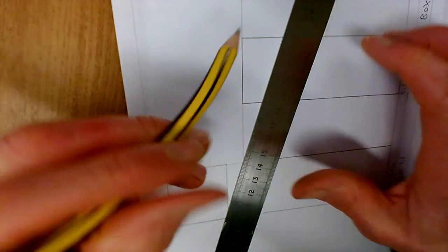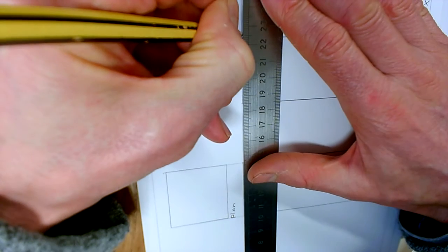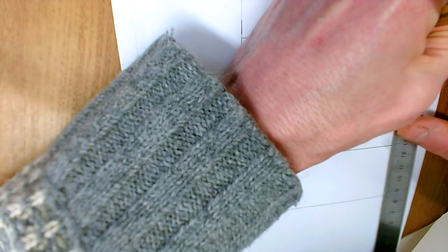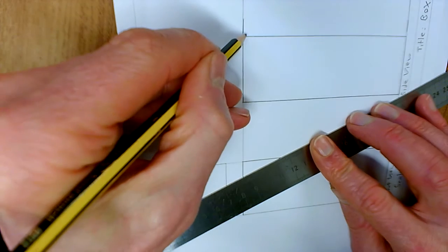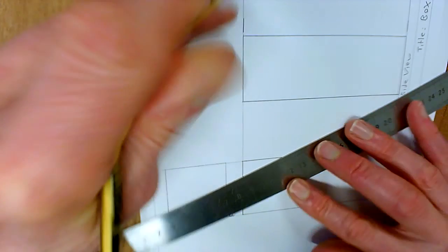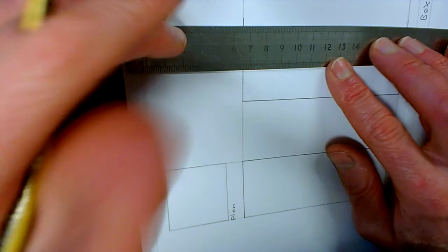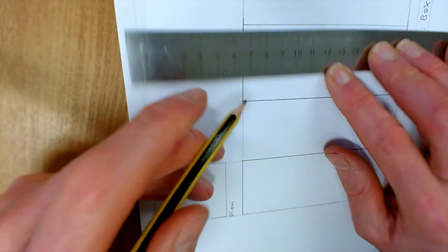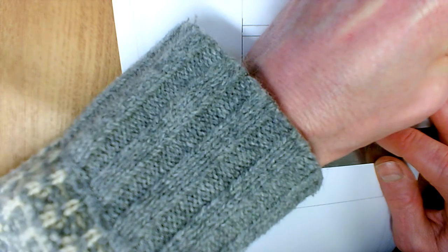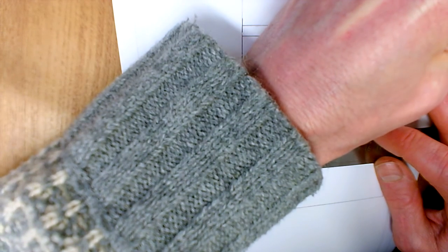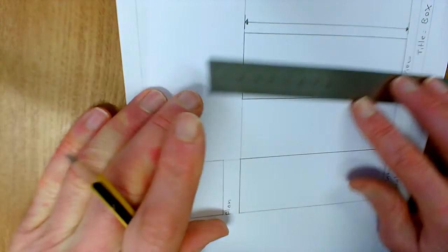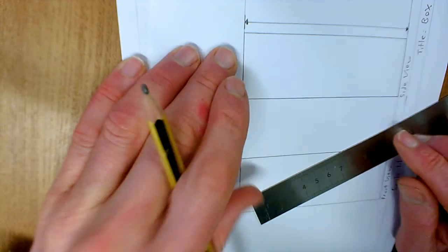So again, we've got two leader lines which go to the end of the object where you're measuring. Remember, these are slightly lighter than the actual drawing itself. And again, don't forget, these do not touch the object. What you're then going to have is, in this case, a vertical line running between those two leader lines, and then again you're going to have some filled in arrows. And we said that was 115 millimeters.